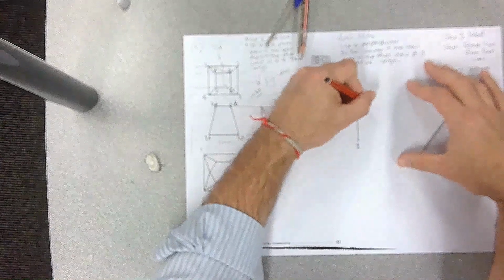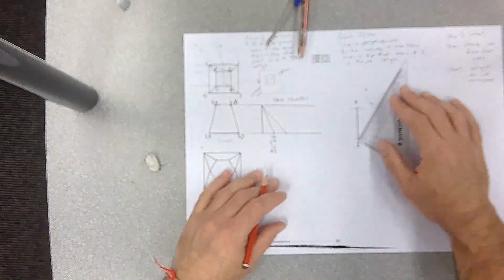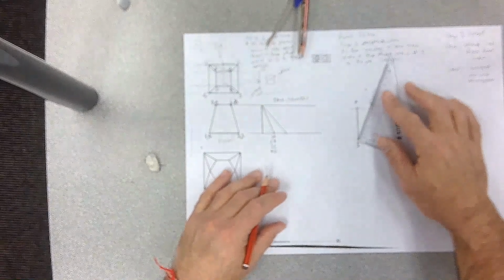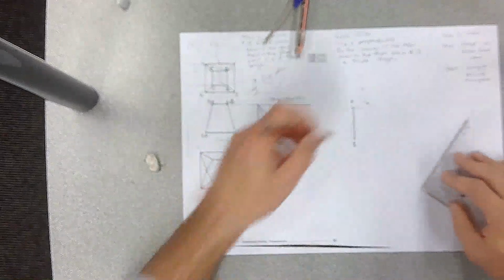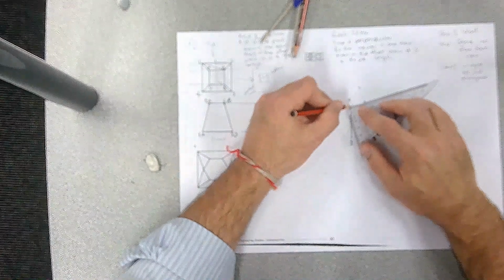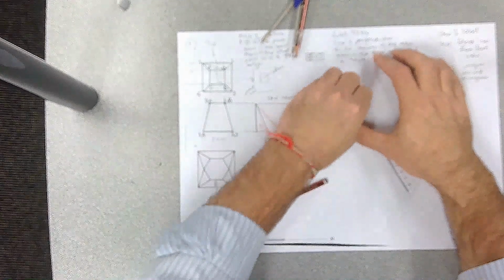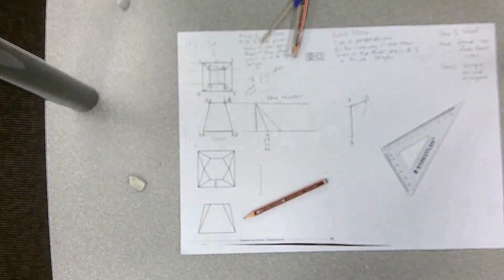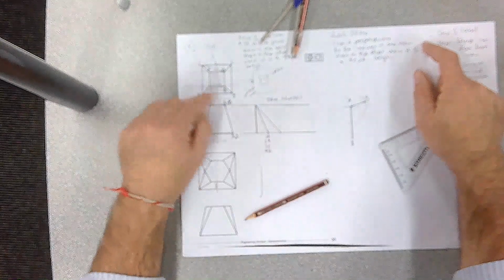So our first line happens there. And if you were to measure between here and here, it should be 5 centimeters long. Okay, which it is, 5 centimeters. So we swung our arc, we've got our point. We can now go A to B. So you should be following me along and stopping this video and starting this video each time we do one of these swings. Now we've done A to B, we need to go 1 to 2 on the bottom.